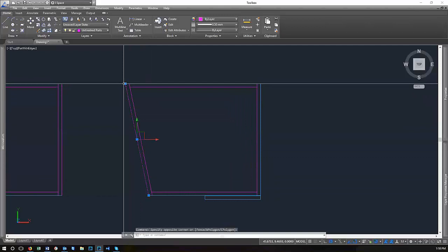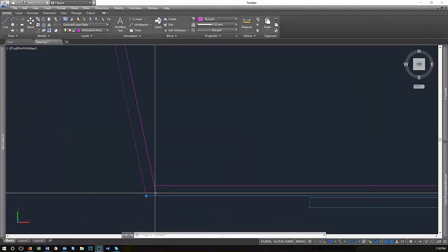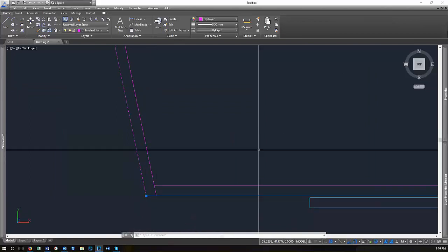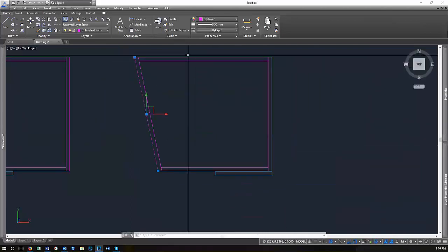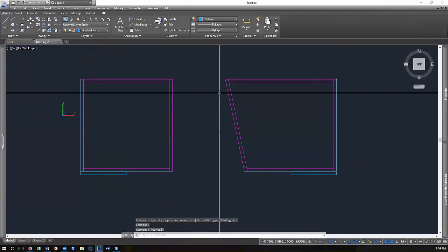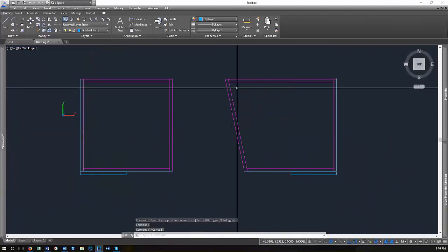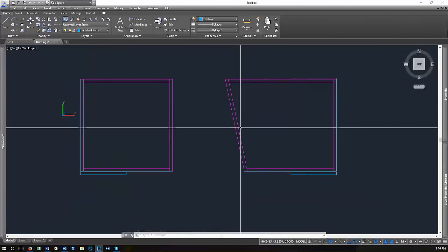I wouldn't necessarily want to use that one because I do still want the angle, but the length of this line plus the extra length on this for the angle would give you the length for that part. So it's a little over 24.5. So you can use the stretch command to create objects that are lengthened on one part, or extend, or make field modifications, or change dimensions.